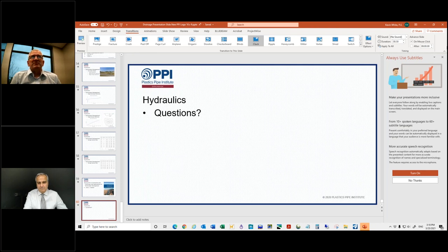from a statistical standpoint. So generally, when you see people talking about the impact of climate change, they're looking at it more from an extreme event situation. Let's say we did a design for a 10-year storm. A 10-year storm, even considering the last 20 years of record, isn't that much different than what the 10-year storm was before we had those 20 years of record.